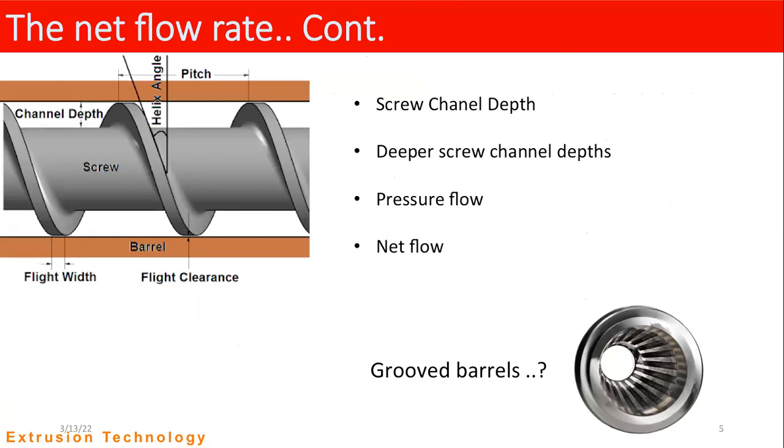So we can use a grooved barrel to avoid or to control backward flow. ඒක නිසා high pressure use කරන extruders වල බොහෝ විට ඔයගොල්ලන්ට දැක ගන්න පුළුවන් groove කරපු barrel එකක්. ඒ කියන්නේ මේක ඇතුලේ groove එකක් තියෙනවා. මේ වගේ. or any design එක වෙනස් වෙන්න පුළුවන්. එහෙම groove එකක් තියෙනවා. එතකොට if it is a smooth barrel surface, you can get an idea about the pressure inside the extruder.